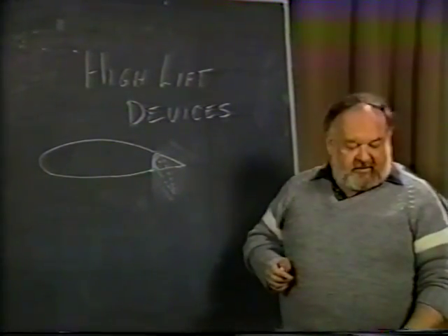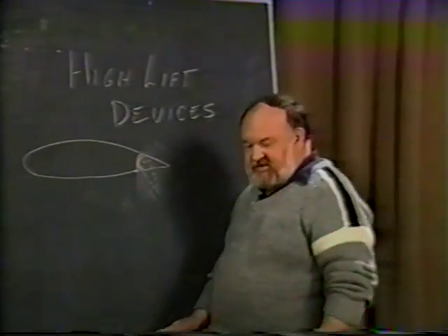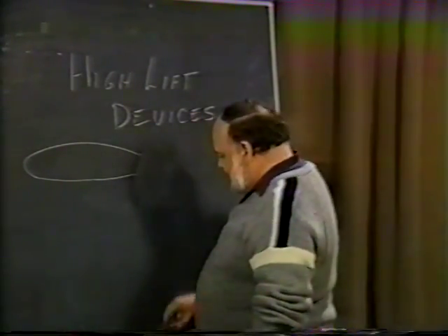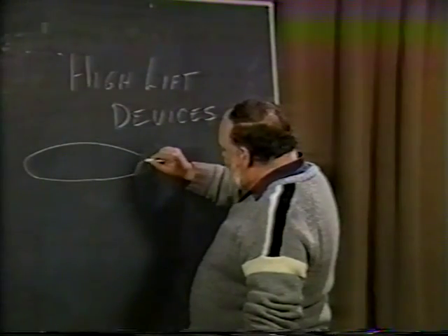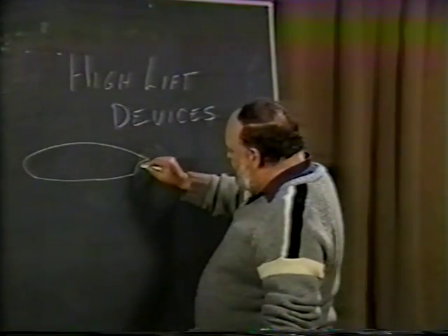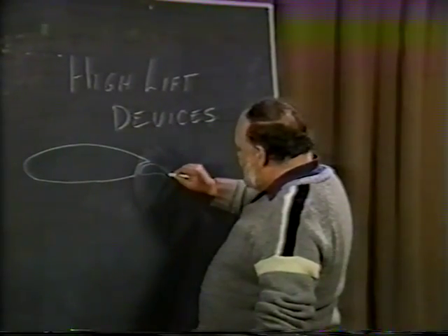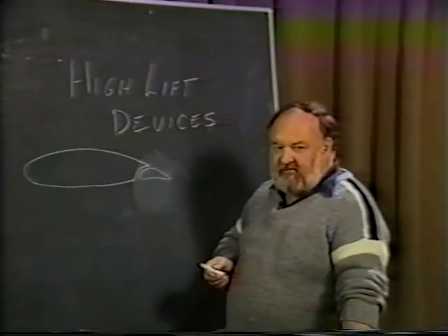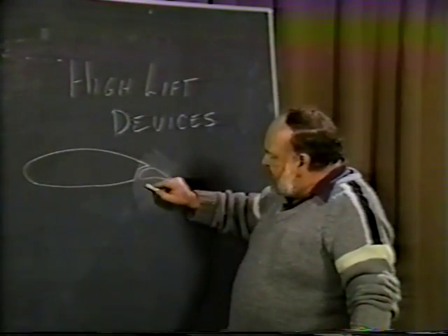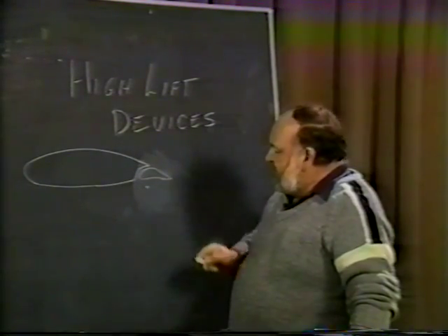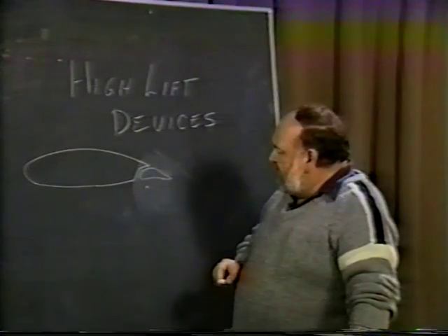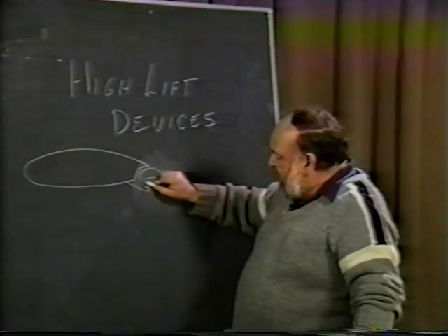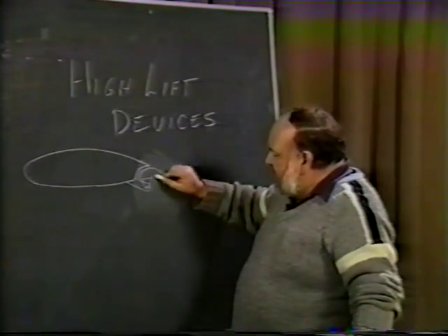The next type of flap that could be used is what is known as a slotted flap. A slotted flap is somewhat similar to a plain flap, except that there is a slot that is controlled between the flap and the main wing section itself. And in this particular case, generally speaking, you do want to hinge it at a point that's outside the airfoil, generally at a position somewhat lower than the bottom skin of the wing, and therefore you probably have to end up with a bracket assembly that will control the flap.